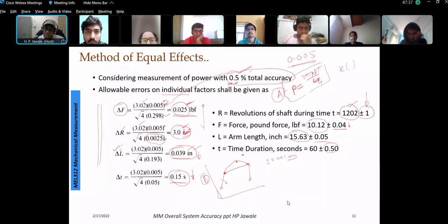So instead of having mechanical instruments used for knowing the values, I will just give the idea. Say now this is a workpiece and I want to know the dimensions of this. The normal method is that I measure this and find it out. But if I use a 3D imaging machine or 3D imaging technique, I will have different light rays passing on this, and with the help of imaging I can know the depth of a particular entity or a particular curve that is generated on this object. And then I will have a very precise measurement where there will be less chance of errors being propagated.